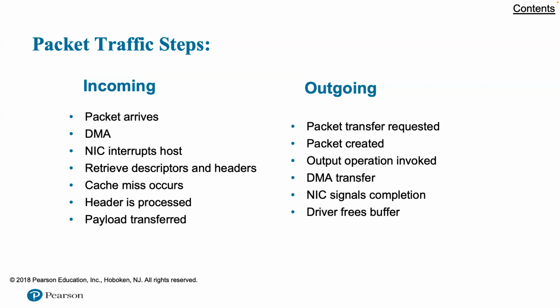Note that the DMA transfer invalidates the cache line in cache, even in the case of a read by the DMA module. If the line is modified, this causes a write back. The core does not do the invalidates. The invalidate happens when the DMA module reads the data.